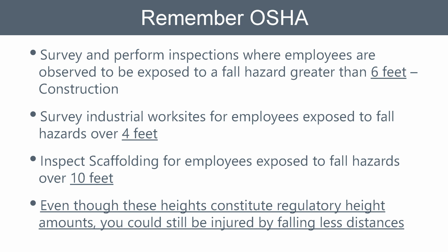So the first thing I want to talk about today is the standards as far as applicability. How many feet up in the air do you have to have fall prevention, fall protection, things of this nature? A lot of times people get these confused, but the construction standard says if you go above 6 feet, general industry is 4 feet, scaffolding is 10 feet. There are some more, but I won't get into those today.